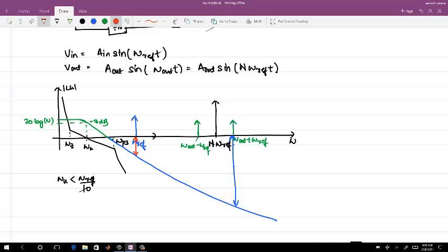No, the phase transfer function is phi out by phi in. But the confusing part will be the loop filter, which you are not considering with respect to the carrier. The loop filter part which you are still considering has a zero at something lesser than omega u, which is real and is not being translated. So there is nothing like shifting the frequencies in the loop filter.